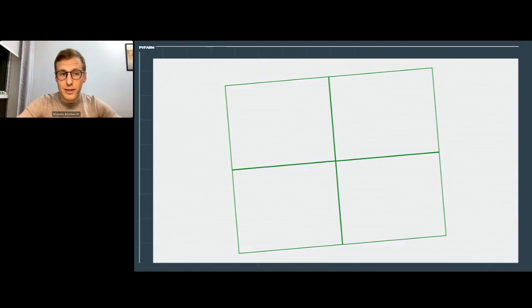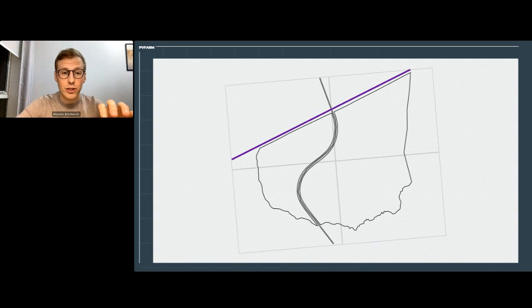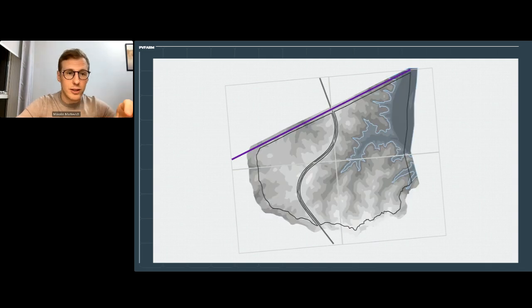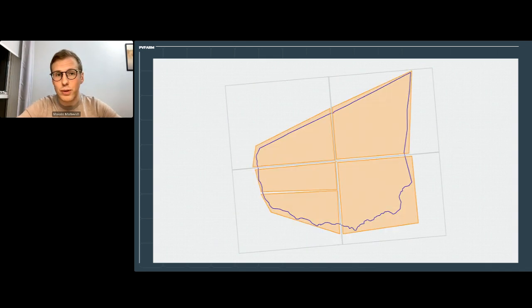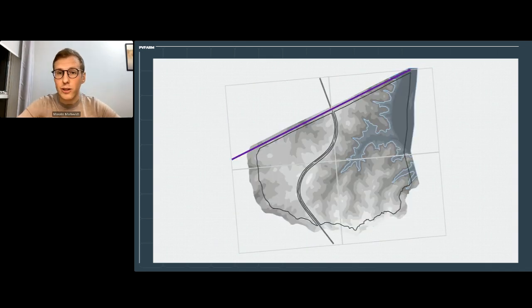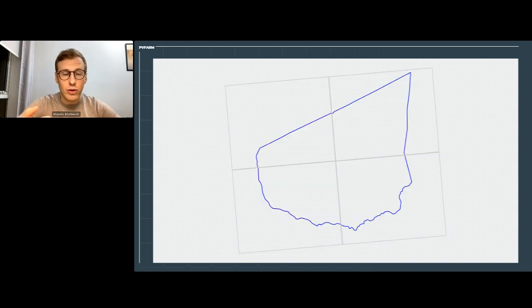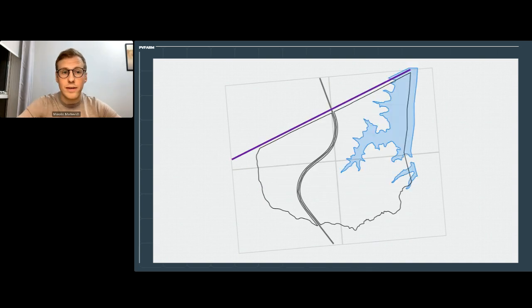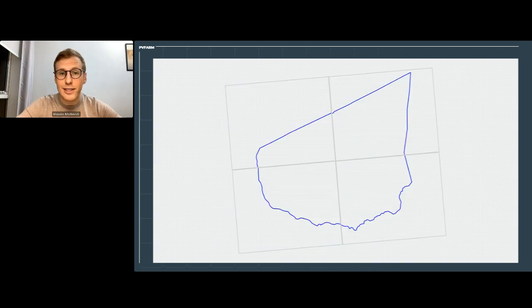Everything starts with defining the buildable areas. The transition from section to parcels to buildable area is shaped by code requirements, which dictate setbacks, easements, land use constraints. From there, contextual factors like topography, hydrology, infrastructure further influence the layout pattern, and they guide how the site is ultimately designed and optimized.